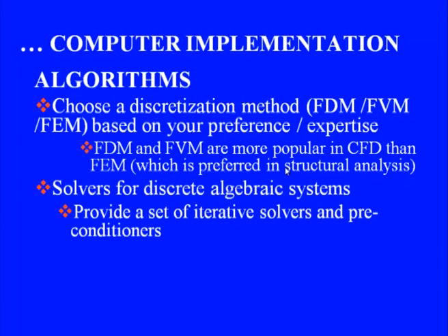Now, next is solvers for discrete algebraic systems. In our usual code, we should provide a set of iterative solvers, and of course these iterative solvers require what we call preconditioners. These two aspects we will consider in our next module on solution of algebraic equations. I have not mentioned any direct solver, because in our usual CFD, when the grid size is pretty large and the number of nodes is very large, we would rarely if ever use a direct solver.